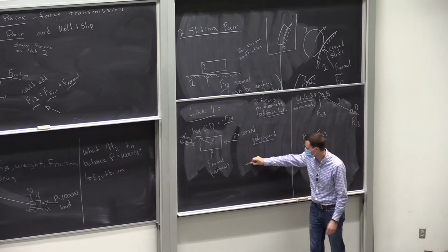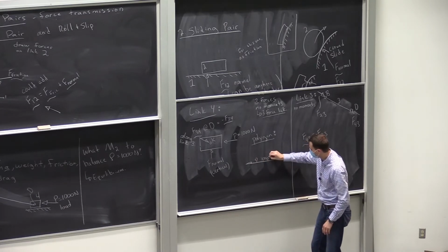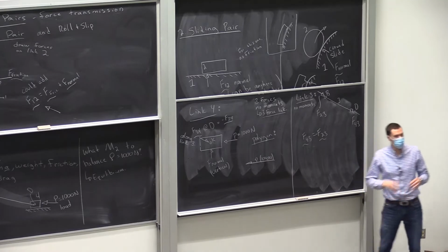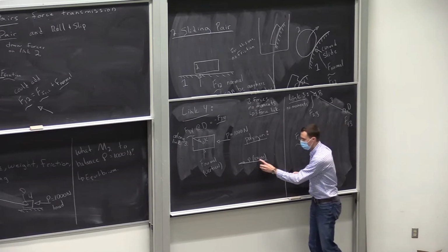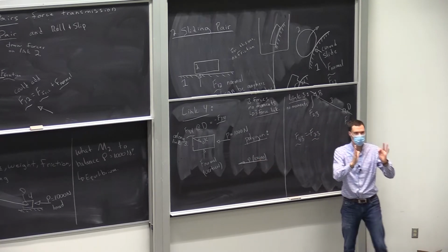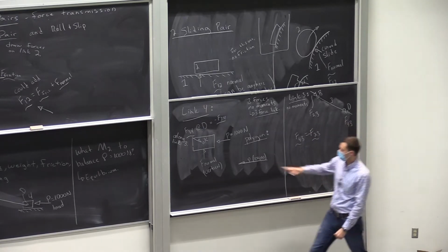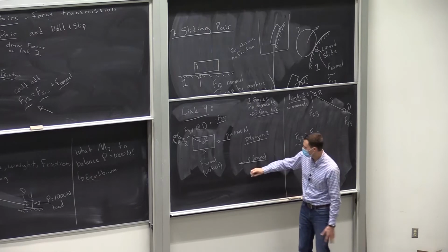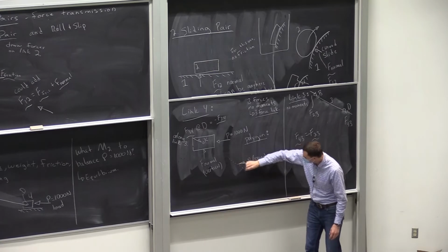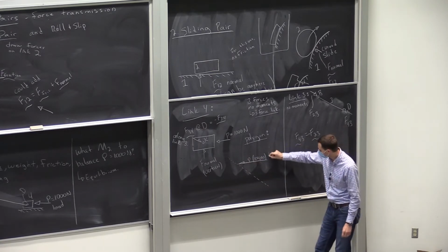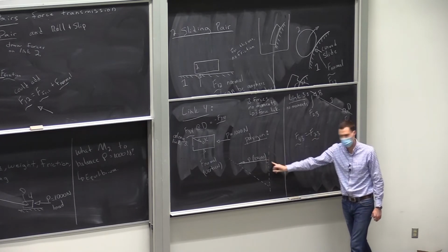So first we put on what we know. P is the only one that we know. Okay, and you need to do a scale diagram here. So you choose a scale that makes sense for you, that fits on your page. Maybe do 1,000 newtons is 5 centimeters on your page, whatever fits in nicely. Define your scale, and then put the other directions on. So I'm going to put 3/4 over here. Okay, and the normal force is vertical. So that happens to be, for this one, a right angle here.